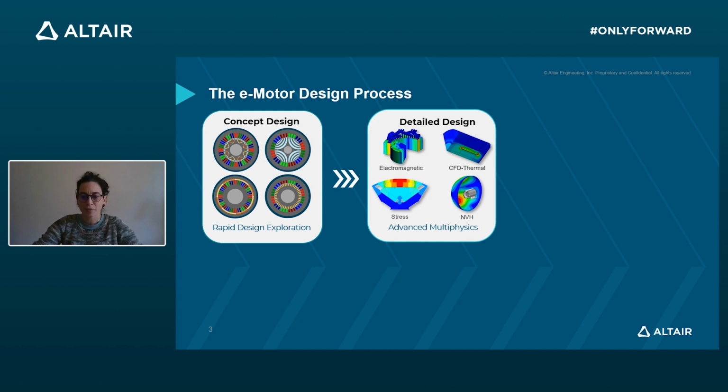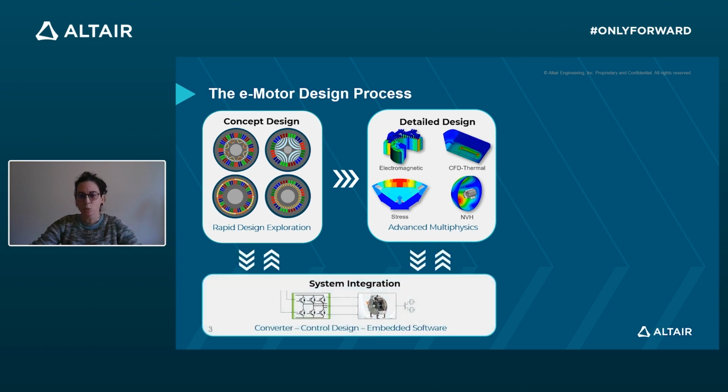So we have specific tools for each of these fields, but we also have a single tool named SimLab that includes all of these solvers and offers the user a simple multiphysics workflow. Both of the design levels offer the possibility to link the motor with the system modeling to include inverter strategy, so the control and global loads to the machine.